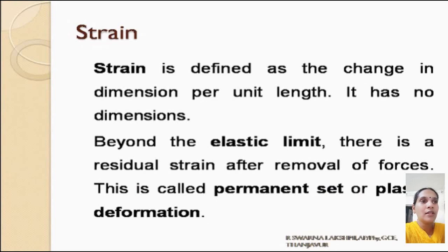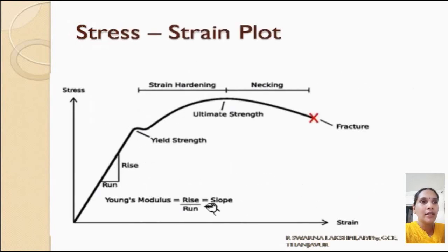So, the stress versus strain plot is as seen for any material in general. And we have come across the stress strain plot while discussing about the properties of material, especially elasticity, in your first semester. So, initially, when a deforming force is applied, the tensile test specimen shows an increase in length, and when the deforming forces are removed, the material regains its original shape. This happens up to a particular point called as the elastic limit. Hooke's law is said to be obeyed in the elastic limit.